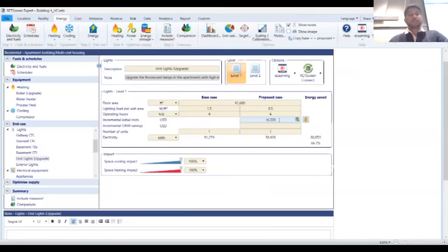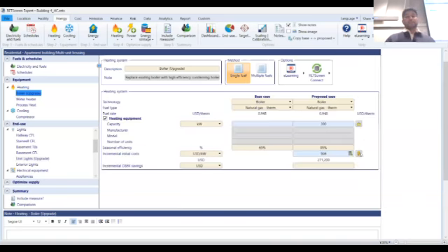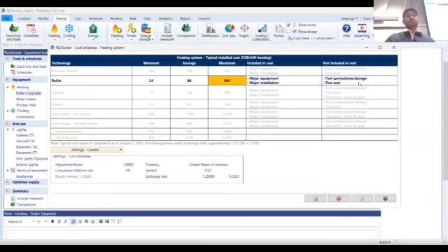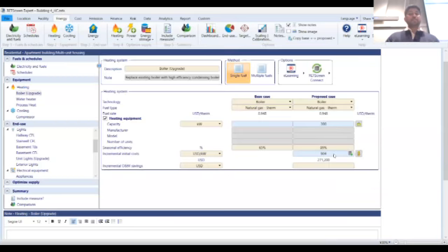If you want to just adjust the numbers, let's say you want to add 20% to the 16,000 cost that you see, which is going to be roughly a total of 20,000, I can just manually change that to 20K. So the cost database is a reference point. If you want to use those costs, you can. But alternatively, you can also update the cost if you want to add certain costs that have been missed through the database. For example, we saw in the boiler upgrade, the cost did not include fuel connection, storage or flue vents. If you do know the costs associated with those items, you can simply add them and it will show up in RETScreen. But that's something that you'll have to do manually.